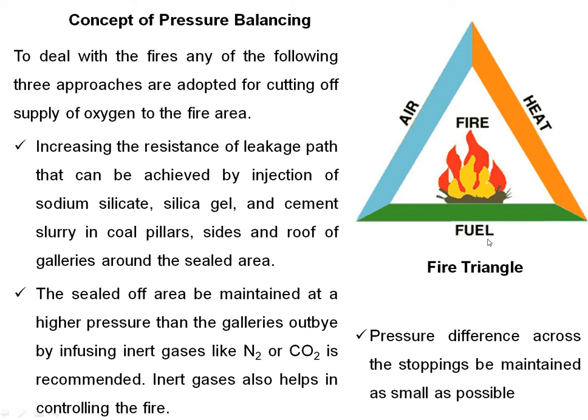You know, from the surface we are pushing nitrogen through a pipe or a channel so that it can go directly to the deep panel, and that is the most important thing. Every full panel will be sealed at that time, and only that N2 pipe will go to the panel, and from the air sample pipe we will get the readings of carbon monoxide, carbon dioxide, CH4 methane percentage, ethylene percentage, as well as ethane percentage if it is there. Okay, and most important is the oxygen percentage. If the oxygen percentage is less than 12%, there is no chance of fire.